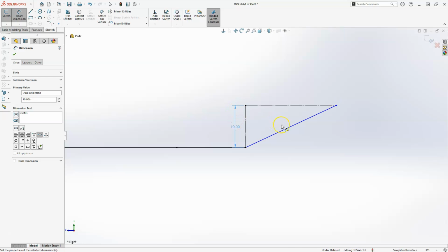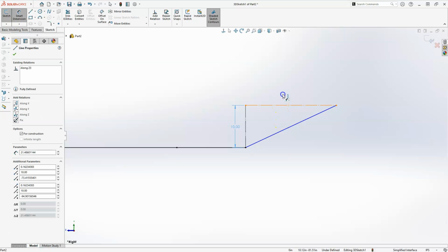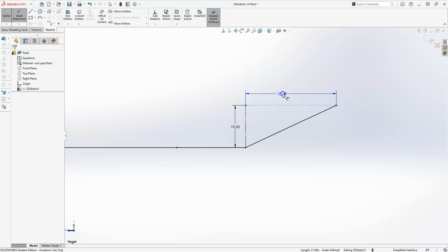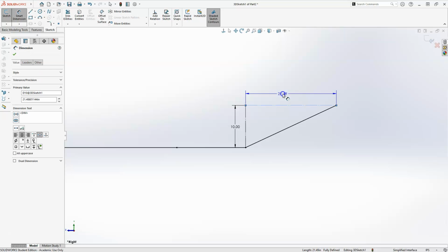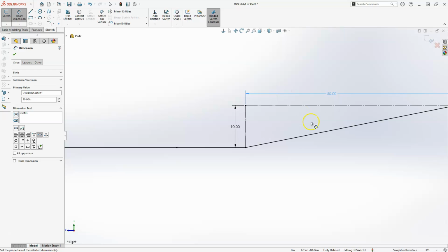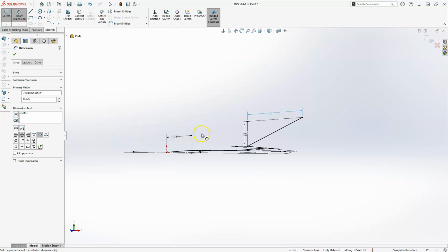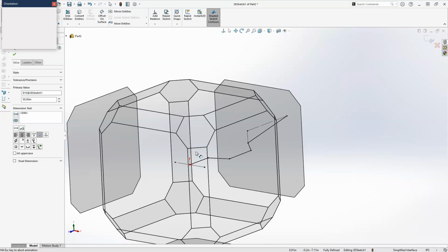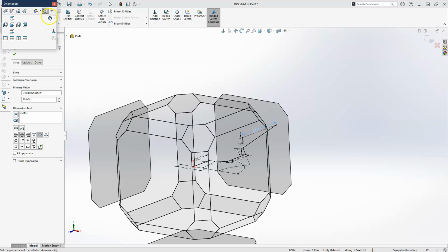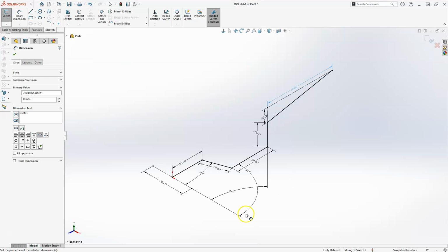And I can also refer you back to, I've done this video using Inventor. The kind of same principles apply to a certain degree here, but this is kind of how you have to create some of these rectangular components, right? So there's my 10 and there's my 50. And now you can see that here is my three-dimensional shape. Let's go ahead and hit the space bar, and I'll just tell it to go to an isometric here. And now you can see my three-dimensional shape here, right? So it kind of comes around and it goes up, and you can see also that it's fully defined.